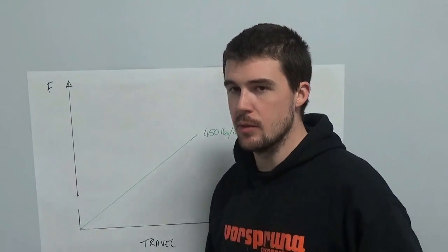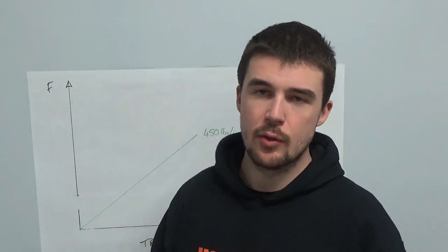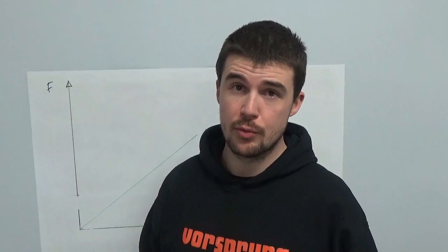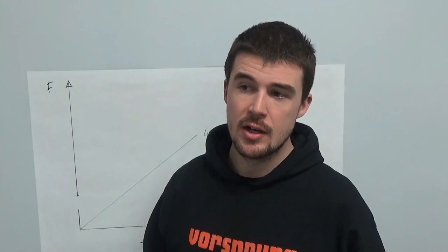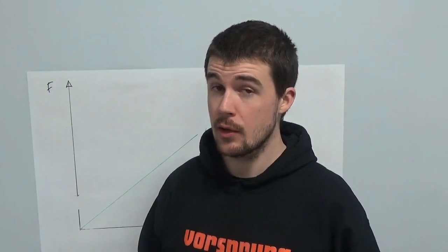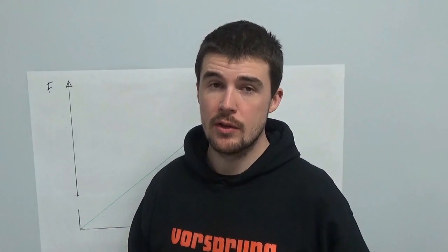If you are genuinely feeling that your spring rate is softer with the titanium spring, there are several possible explanations for this. First of all, it could be that your spring is actually softer. Not all springs are exactly as they are rated. Most quality ones from the brand name manufacturers are actually quite close, within a couple of percent. Some of the cheaper titanium ones are not so accurate, some of them are bang on.